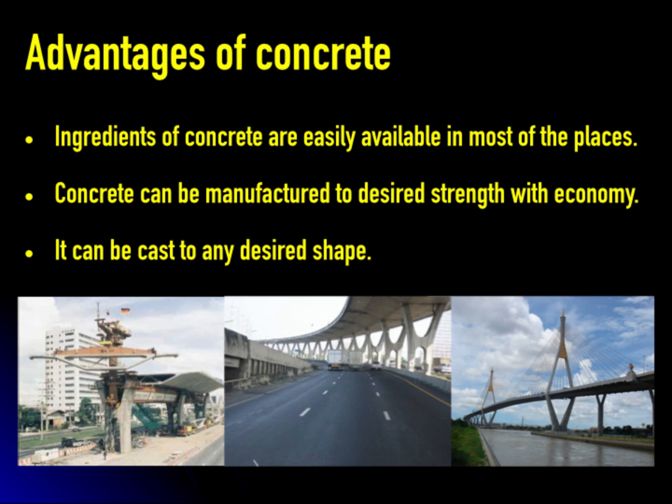Another advantage is that the strength of concrete can be customized by adjusting the mix proportions. For example, high-rise buildings require higher compressive strength than houses or roads. By increasing the cement content and reducing the water content in the mixtures, the compressive strength can be significantly improved. Moreover, in its fresh state, concrete can be poured and shaped easily according to the formwork used, as shown in the accompanying slide.